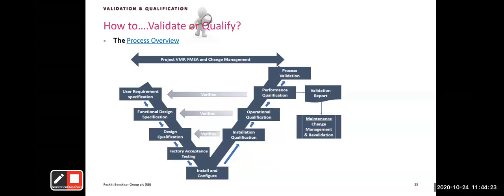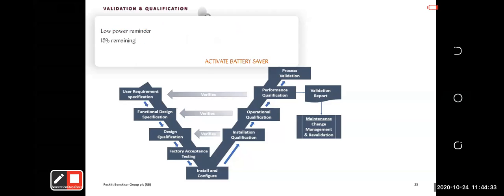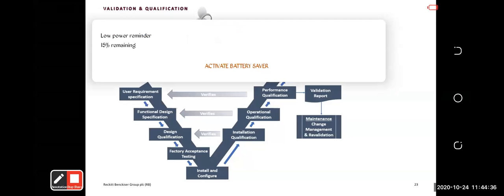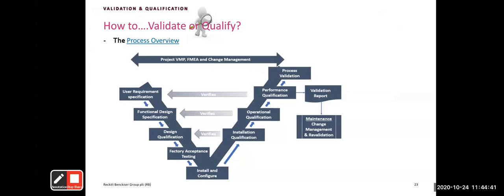So during your OQ, you now want to confirm your operational checks, which goes in line with the design that the manufacturer has said he has designed the equipment. So you'll be looking at checks in line with the operation manual of the manufacturer in most cases. So they'll tell you, plug this socket to this position, and you will see an audiovisual response, a beep and a sound. You do that and you check for that response. That's an operational check. They'll tell you, look at this LCD, press this button for 5 seconds. You'll get this response. That's an operational check. So there are different operational checks that you would have to go through. You would have highlighted it in your operational check qualification protocol, and then you get responses from them.